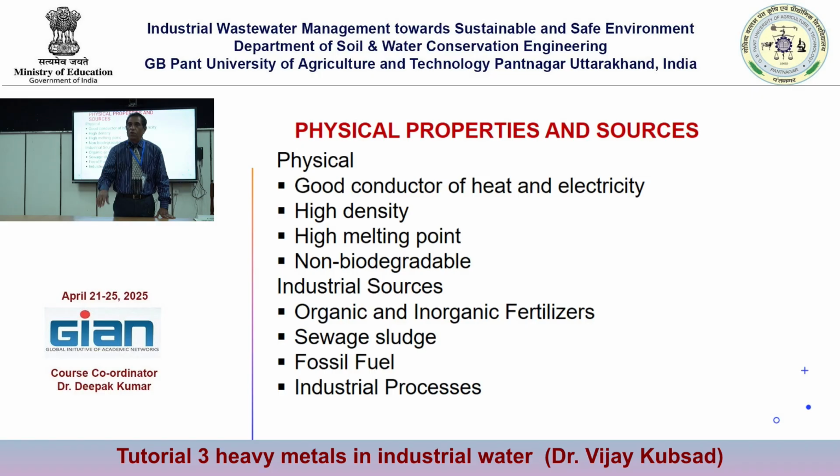So if you do a BTEX test and get 1.5 or 1.4, you are safe, right? But if benzene is 1.3 and other components are 0.001, you are already violating. You are already at risk, because benzene should not be more than 0.5. But what you authorized was BTEX 1.5. You did not say benzene concentration should not exceed 0.5.